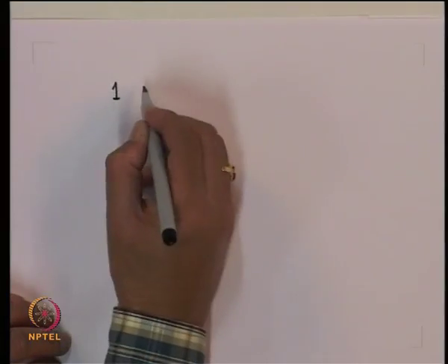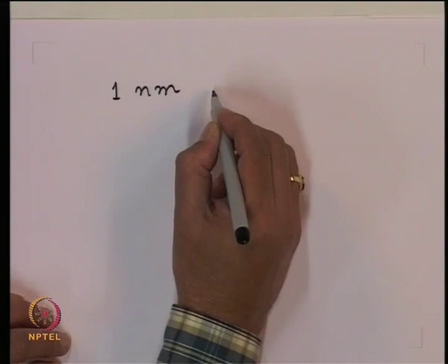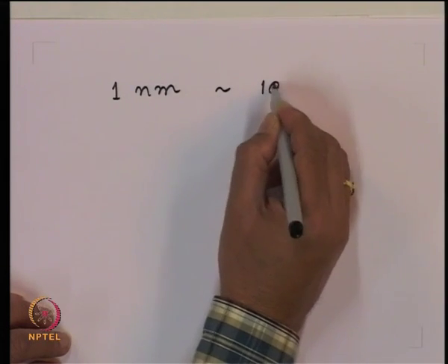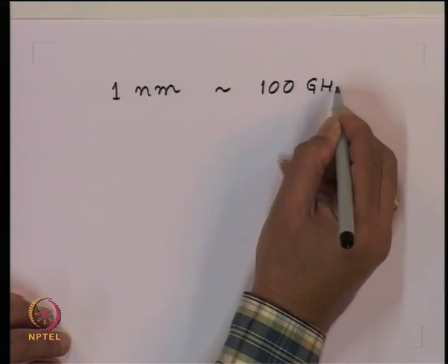And we have seen if we go to typically 1 micron wavelength kind of signals, approximately 1 nanometer spectral width is 100 gigahertz. So, we have almost a rule of thumb that typically 1 nanometer is of the order of 100 gigahertz.